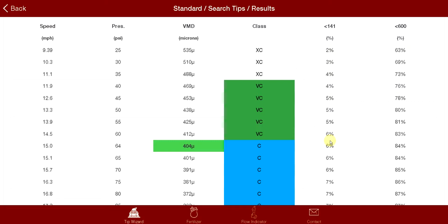To visualize it, as soon as the spray leaves the spray tip, droplets that size are more than likely to be traveling 3 to 6 inches outside of the spray tip, and then dramatically slowing down to the point where there's just gravity and spray speed and wind speed taking it down to target. Which, as far as trying to maintain control over that stuff, is pretty much impossible without extra systems or alternative measures there.